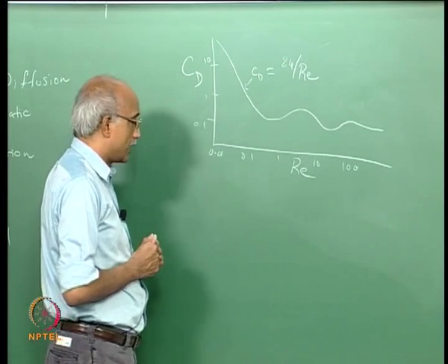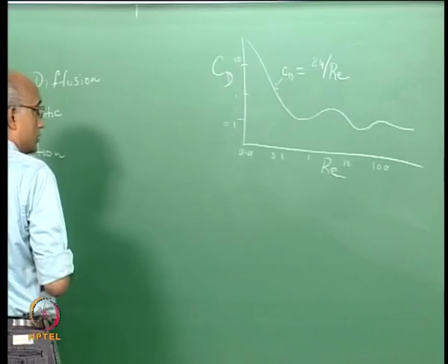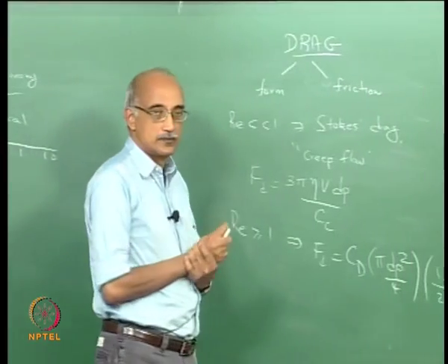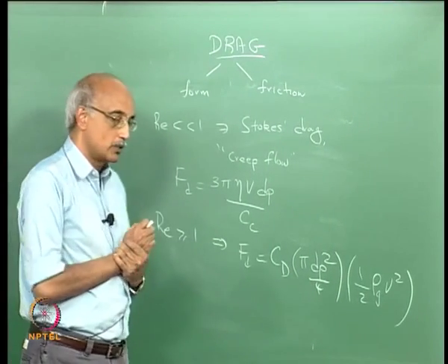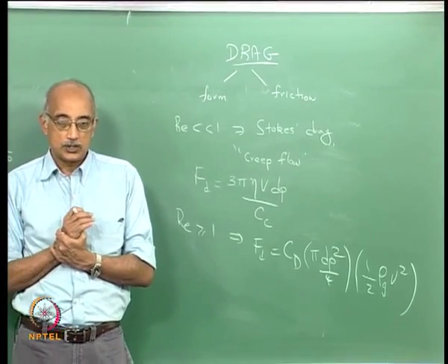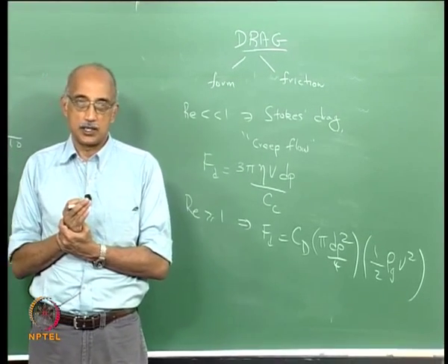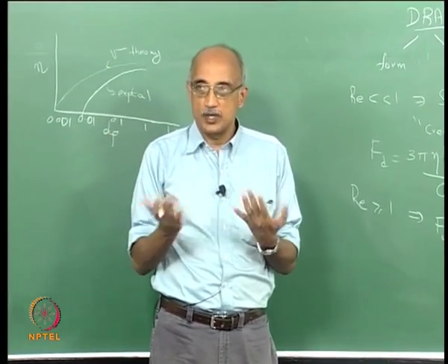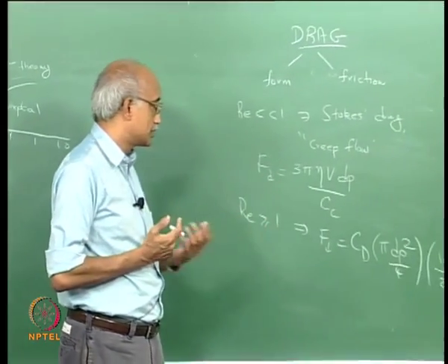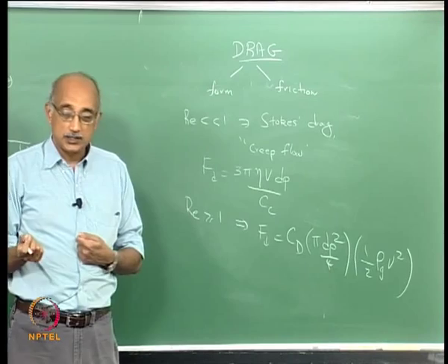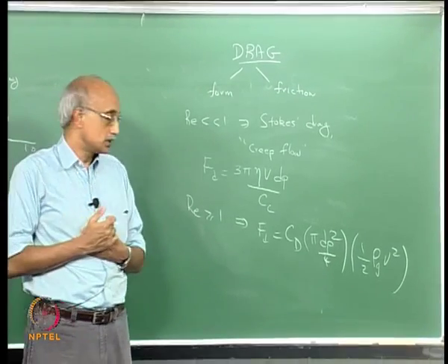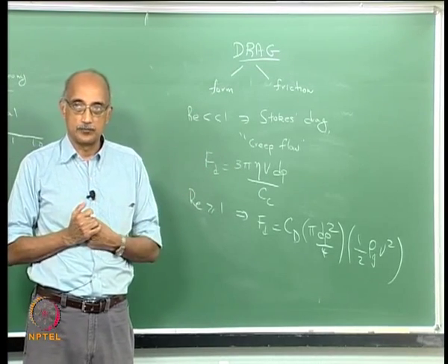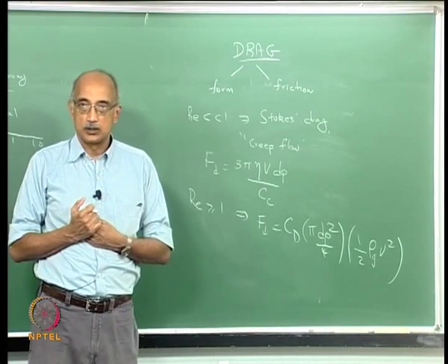So, when you look at drag force, the expression for drag that we wrote down again contains a lot of useful tips. One of the questions that you always face is, do you want to minimize drag? Again, it depends on the application. If this particle is, let's say, an airplane that's flying, then you want to minimize drag. So, what would this tell you? If you minimize the viscosity of the fluid, the relative velocity, and the size of the object, whether it's a particle or a plane, that minimizes your drag force.